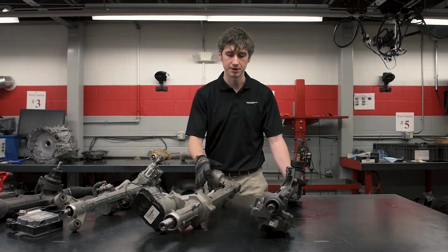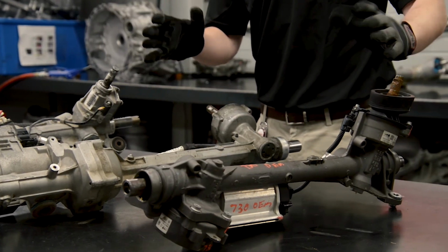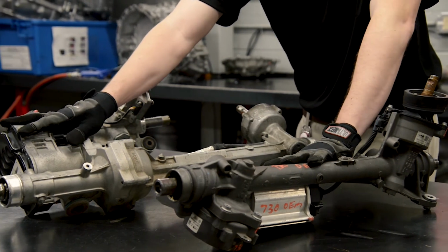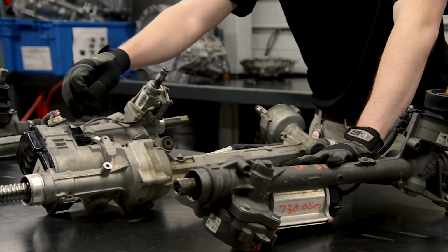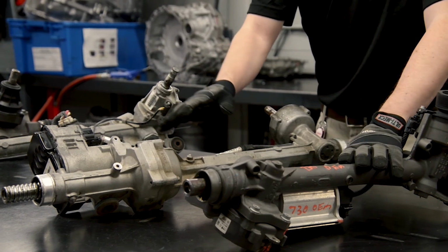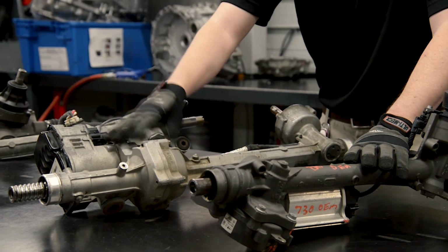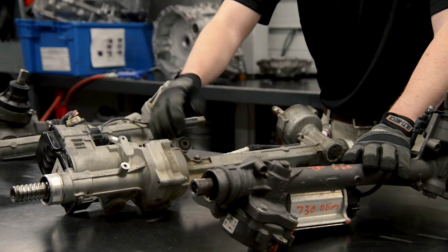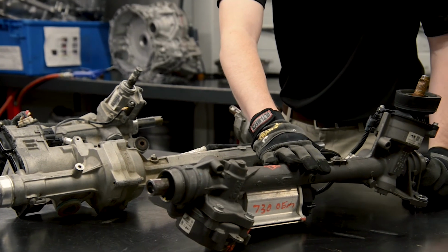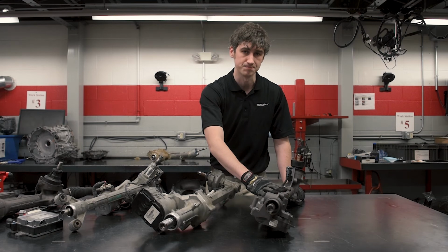So starting out here, these are dual pinion racks. Both are going to have the same components we touched on, torque sensors. Both of these actually have modules bolted right to the rack themselves, which includes the motor and the electronics. What's going to make these different, though, is this rack here is actually belt driven. So we touched on that previously. Motor is going to drive the rack bar with a belt. This rack, however, is actually driven by a worm gear. So instead of it being a belt, motor is going to drive the rack bar with a worm gear.